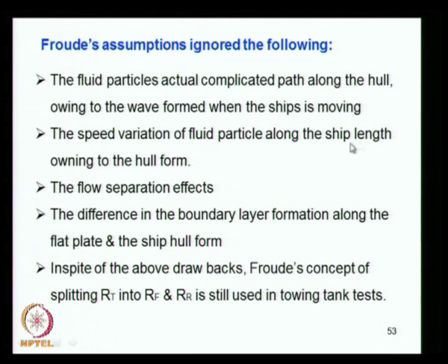The speed variation of the fluid particle along the ship length owing to the hull form is also ignored. Here we used the flat plate formula, but the water particle velocity around the flat plate and around the ship, which has a 3-dimensional form, are different. When there is a curvature, there will be an increase in water particle velocity, which is ignored in the assumption, because we are using a flat plate formula for the estimation of frictional resistance.